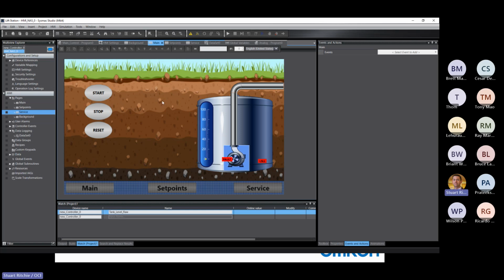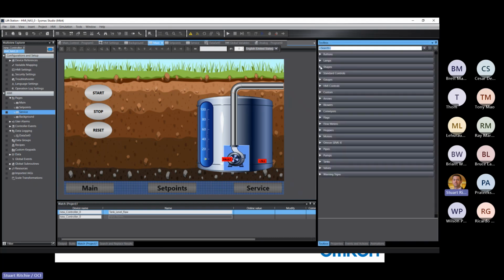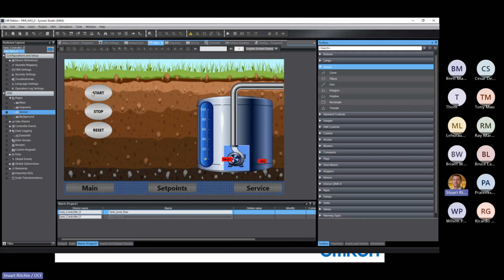So one thing that the buttons in the control room have are LED indicators on the start and stop push buttons. So what we'll do next is we'll go into our toolbox and we'll grab two shapes and we'll place them behind the start and stop push buttons. And they will reflect the color of those LEDs, and they will flash or they will be solid according to what the button is. And this will just help us show the operator what mode we're in or if we have any alarms. So I'll get everyone to just drop two rectangles behind their push buttons.